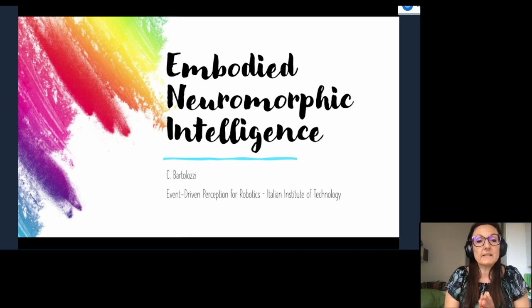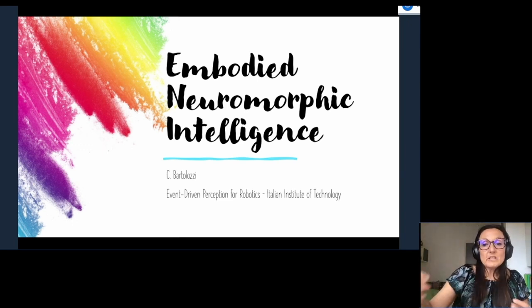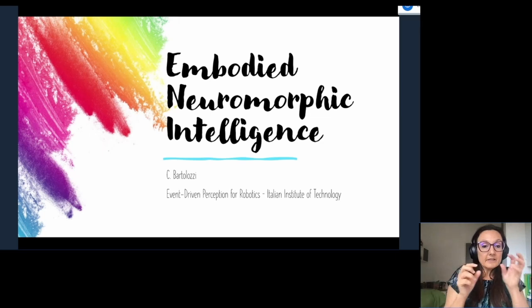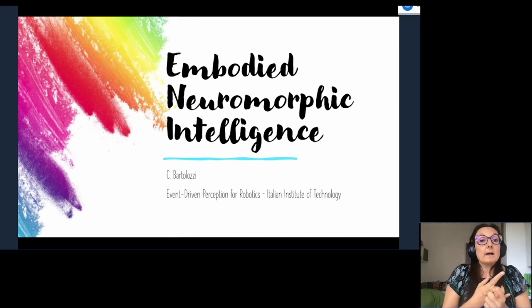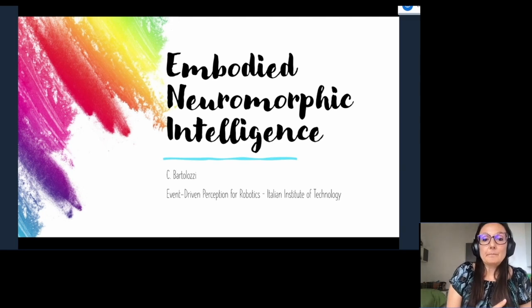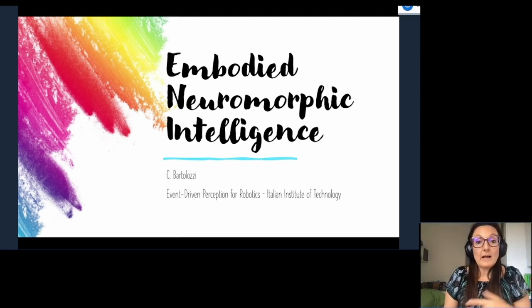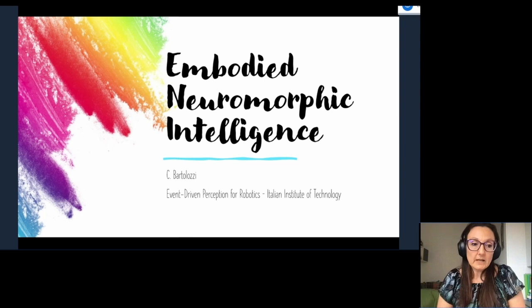What you can observe here is that the camera doesn't send any spike output if there's no change, if there's no movement. To get data, you really need to either move in front of the camera or move the camera itself. And when you do so, the information has very high temporal resolution. Basically, every time you move from one pixel to the next one, you see the movement, and each pixel activates asynchronously. So you have very high temporal resolution, coupled with high compression. If you have a frame-based camera with the same temporal resolution, you have way more data that you send around. You have very low latency because you don't wait to acquire a full frame before sending the information out.